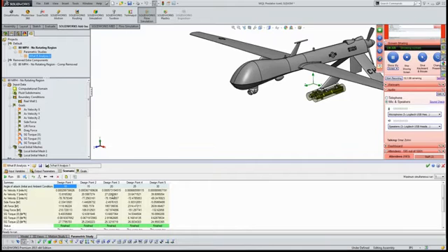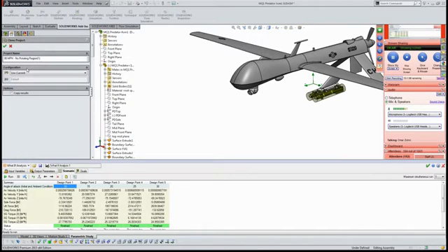And then again, a really nice thing about flow simulation is if I've got it set up for one of my configurations, here's my flow configuration, I can just right-click and say clone, and it's going to ask me what configuration I want to clone it to. So if you have multiple configurations, you can create a master flow configuration and then copy that flow configuration, all the setup, meshing, and post-processing, into all of your other configurations.